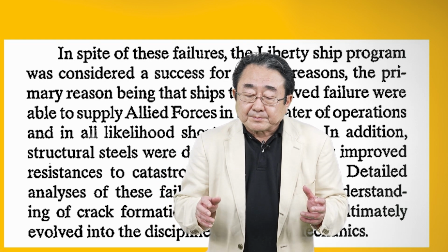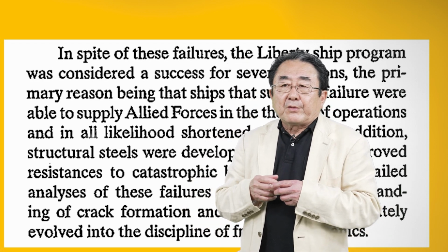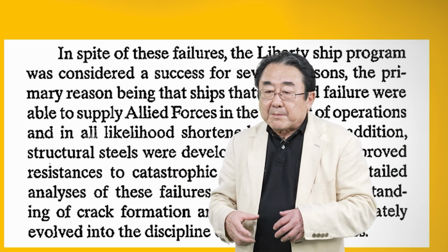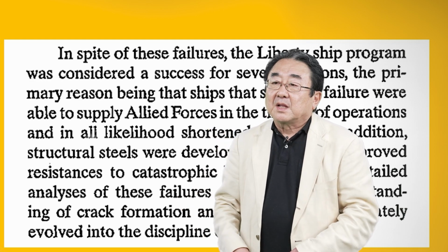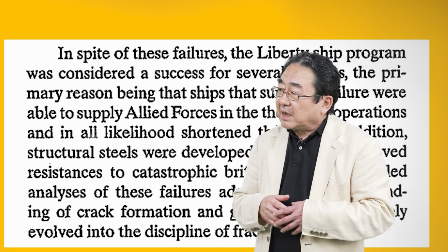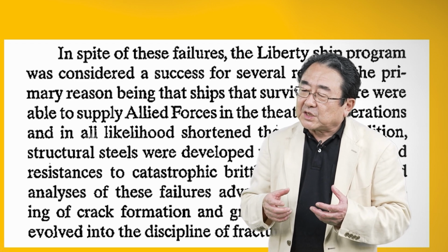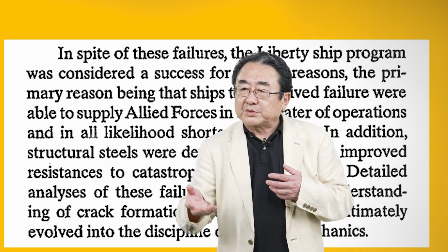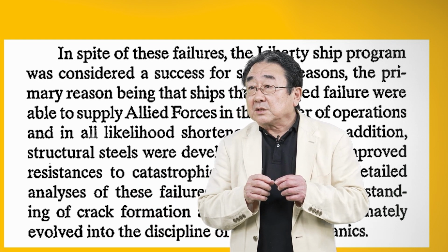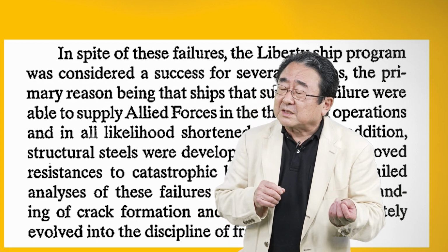When we studied the strength of materials, when we apply a tensile load to materials, we assume materials are perfect, with no defects, no voids. But in the case of a void or some defect in the structure, like the welding part of the Liberty ship, from that discontinuity, fracture initiates and propagates.